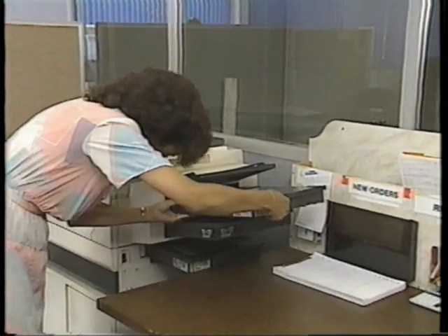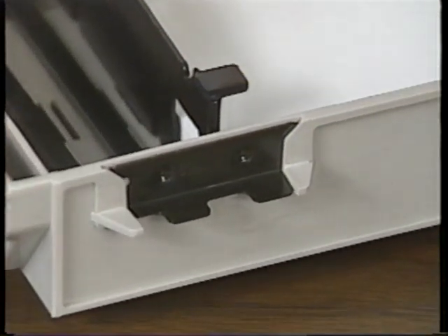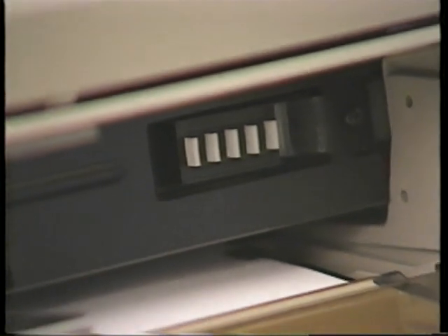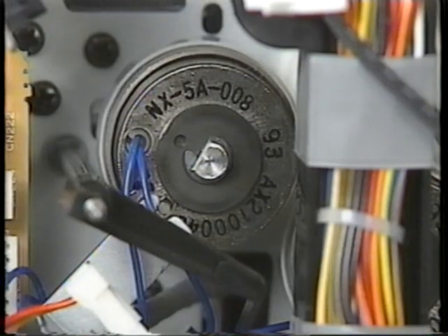In copiers that use removable paper cassettes, a group of switches detects the configuration of special tabs or notches on the cassette. Each paper cassette will activate only certain switches in the group. The resulting combination of open and closed switches corresponds to a specific paper size.